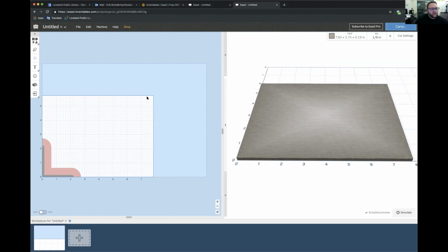Alrighty. So another thing I do want to mention is I talked to you about the limitations of the material. So let's say we have our 8-inch piece of material. We actually are not going to have 8 full inches of design capabilities. What I mean by that is we will not be able to use the entire board, because we have to keep in mind the machine has to clamp down the material to hold it in place for the drill bit to actually drill out.